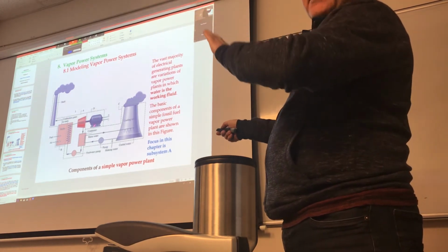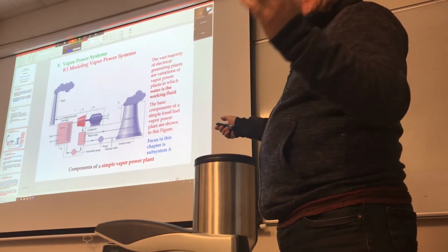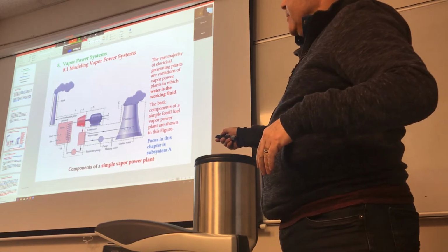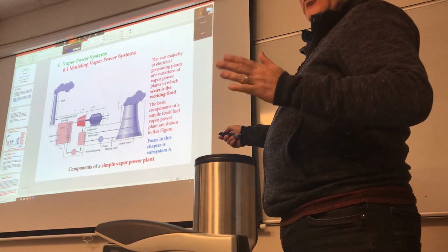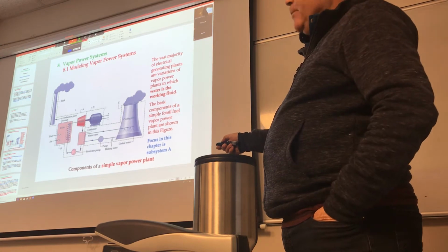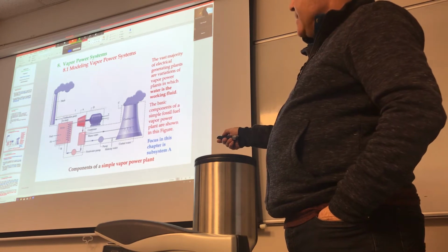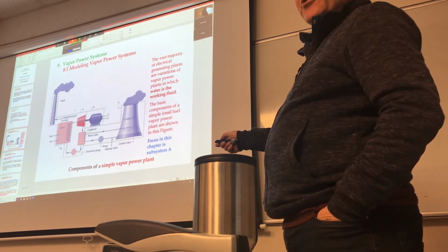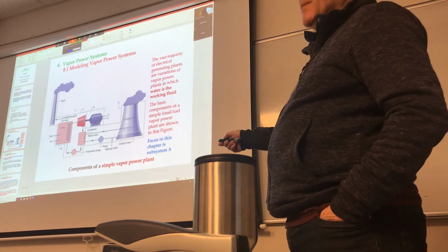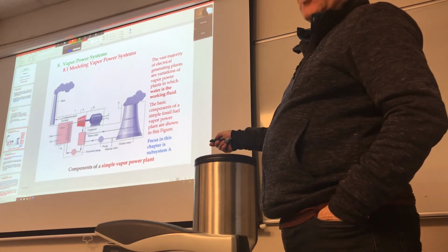Of course, this is not our job, right? Our job starts right here. We're getting a shaft that's turning. That means it's power. And then afterwards, obviously, you get the lower temperature and lower pressure gases that are still hot, by the way, but you don't want to pump vapor, right? So you want to turn that into liquid again by passing it through another heat exchanger. But how is that heat exchanger working? I mean, you can't just be a black box and get cooler water.